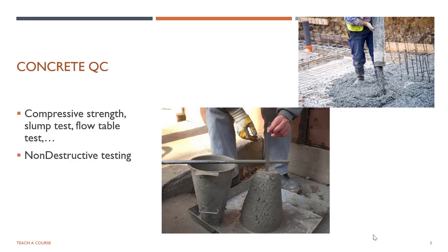Maybe if we have some doubt about the quality, it will be done on the concrete according to the type of the project and so on. Non-destructive tests include the Schmidt hammer or rebound hammer, core test, ultrasonic test, and another way of measuring the concrete thickness.